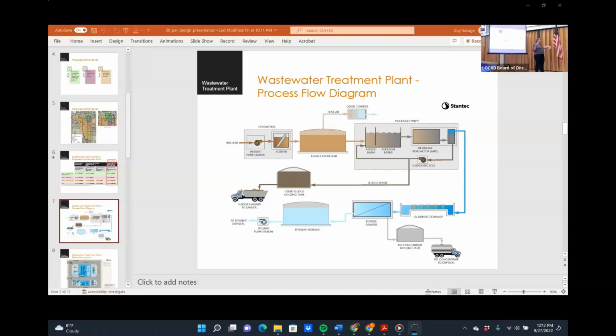That smells bad. It does. That's the worst of it. Pulling out those inorganics, and then that has to be hauled out. So that's another component before you can even treat your water. Because what your wastewater treatment plant does is treat the organics in the water, not the inorganics. Those have to come out. And so that leads to two trains.